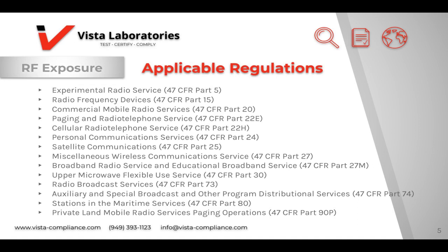We just briefly talked about MPE, which is maximum permissible exposure. These limits apply to all FCC regulated devices in all exposure conditions. There are different conditions, such as fixed exposure or mobile exposure, depending on how far the product is and how it's intended to operate.